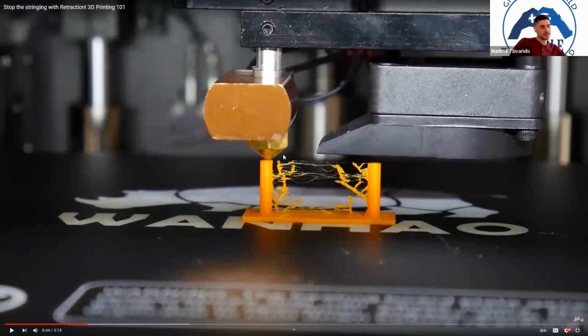If you didn't hear it, guys, this is without retraction, so we haven't clicked the enable retraction button on this example. This is called stringing. Stringing is when the nozzle goes from here to here and prints, and then to here and prints, and then this is what happens. Why this happens is because there is a small part of the material thrown away when you move from here to here. So if you enable retraction, the filament goes back up inside the nozzle when you move from here to here, then it goes back down again and prints.